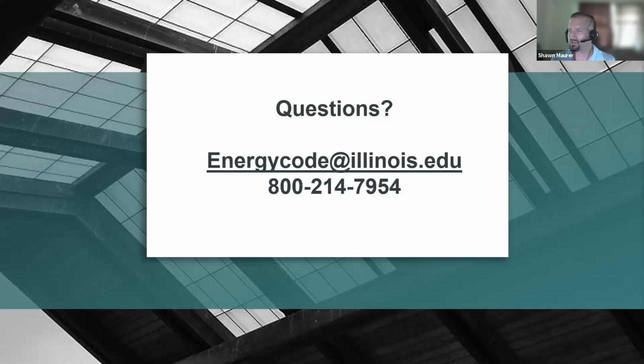I did want to touch back on the task lighting question we got. That is not included in the calculation for lighting power density. If you look at C405.3.1 of the IECC, they have a calculation there for total connected lighting power. It does not include task lighting in that calculation. So if it is included in COMcheck for task lighting, it may be lighting that is included under an exemption, as it's not included in that total lighting power calculation in the code.